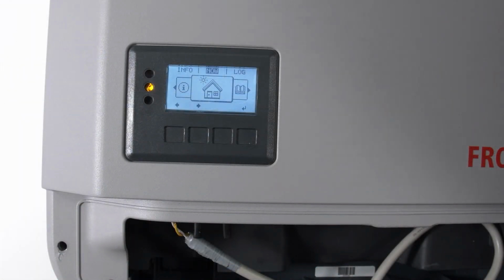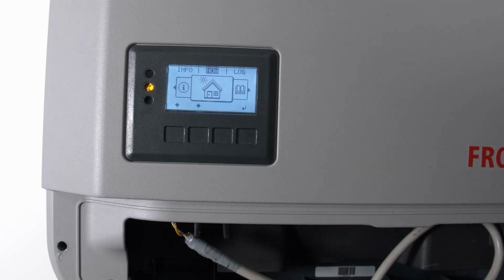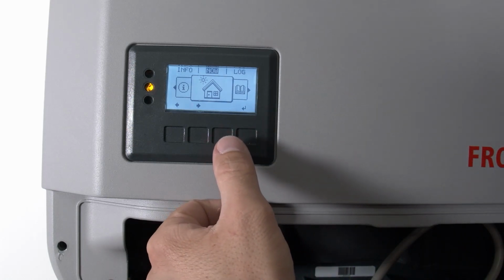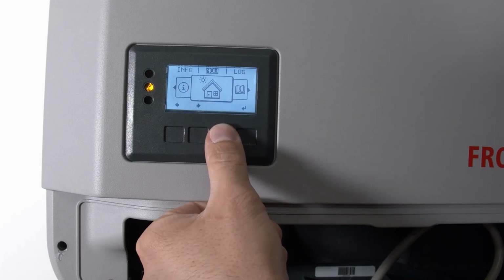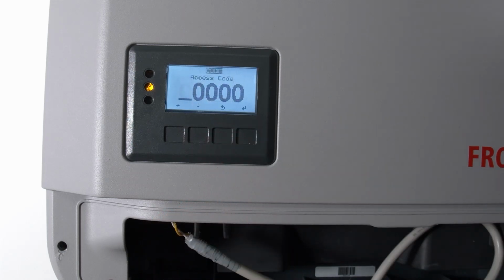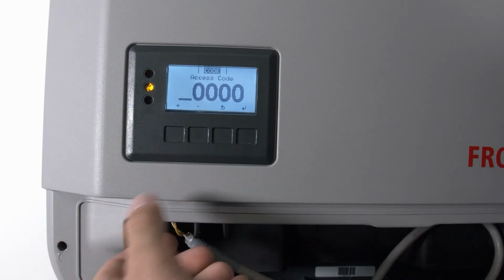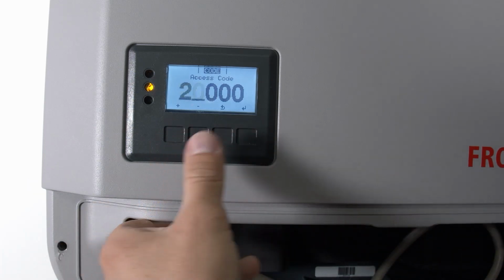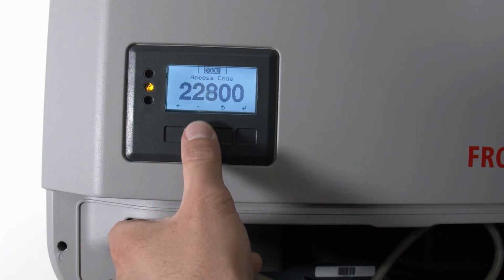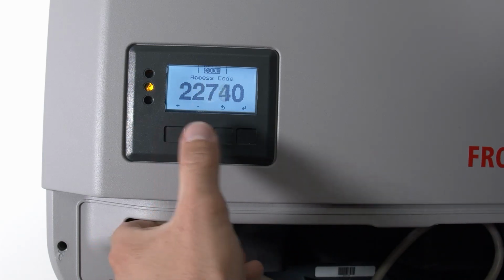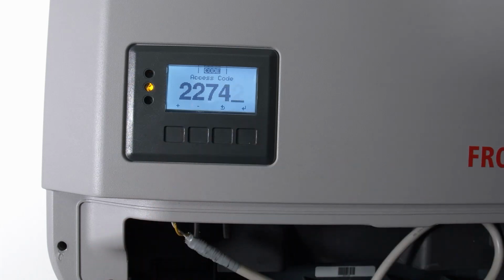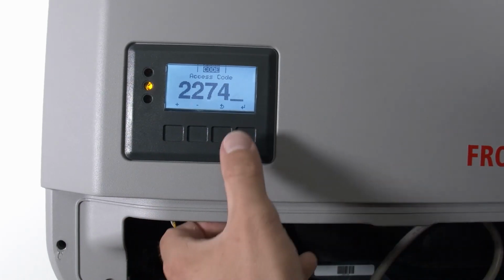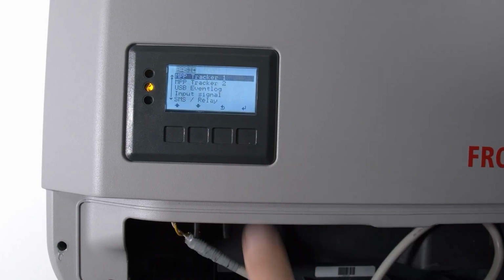After the complete installation of the S0 meter and the snap inverter, finally we have to do the commissioning on the inverter display itself. Therefore, we touch the soft key, the third key from the left side, 5 times. And now we enter our basic code to enter the setup. This code is always the same, it is 22742, and with this basic menu we can enter the settings that we need to commission the S0 meter on the inverter.